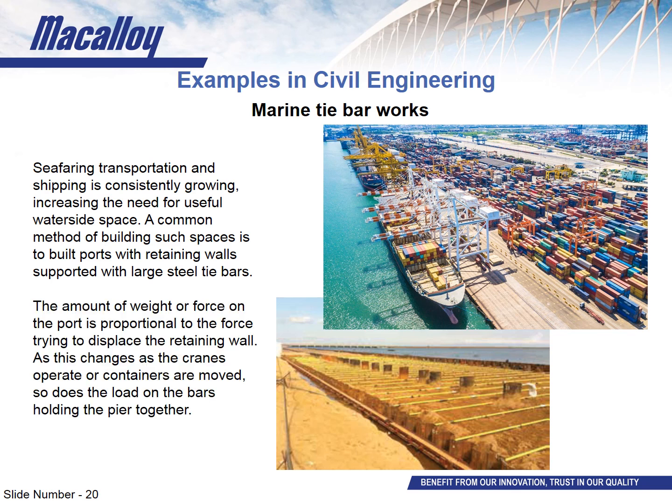As this weight acting down on the port is proportional to the force trying to push the retaining wall out to sea, this is proportional to the load imparted on the tie bars. So as this load fluctuates as cranes move and operate and containers are loaded on and off ships, the load in the tie bars changes. As you can imagine, the frequency of this will be lower than in previous examples, but as there is no way to inspect these bars once they've been installed,